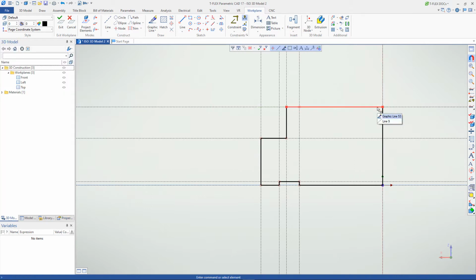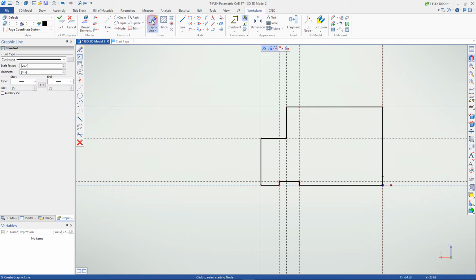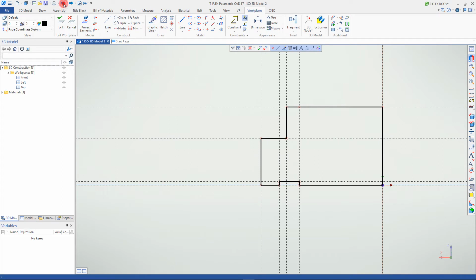When working with construction and graphic lines, it is necessary to take into account and remember that object snapping is always enabled. In addition, graphic lines have a free entry mode. If it is active, then the construction is performed simply in the free drawing mode, without being attached to anything. To turn off this mode, press the option again. Let's cancel the construction and continue the lesson.